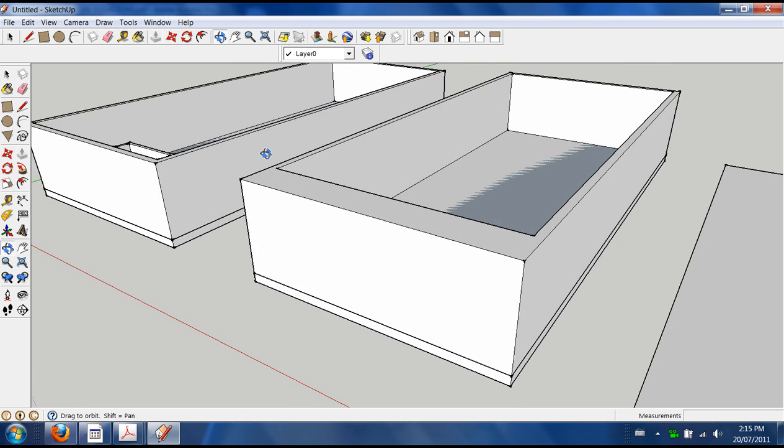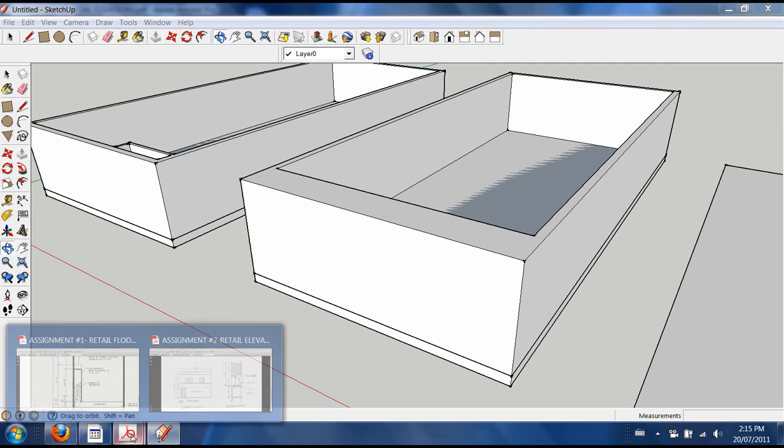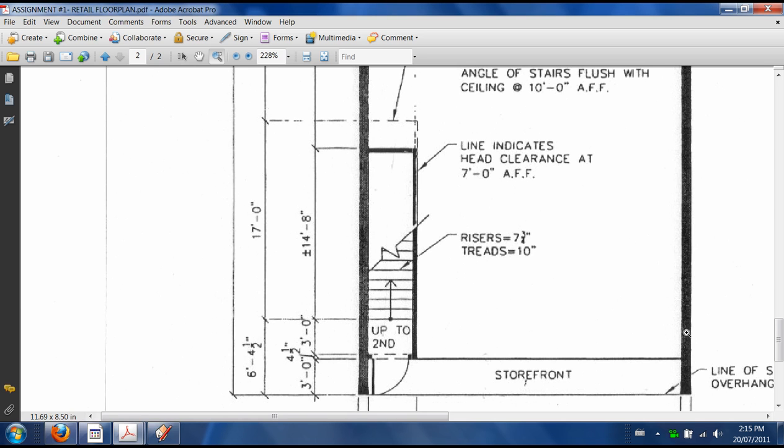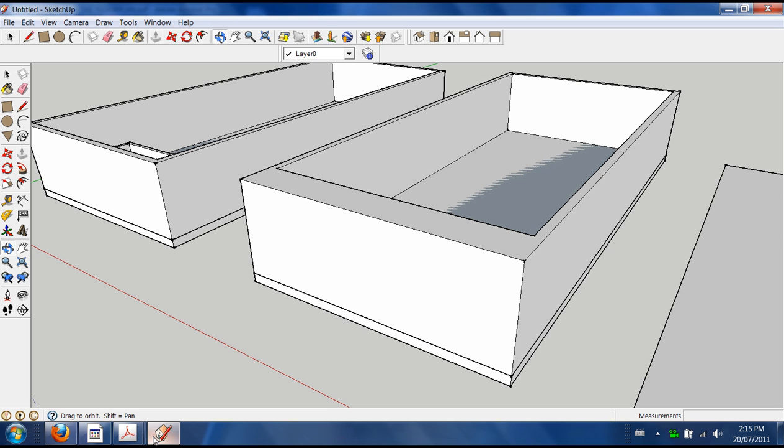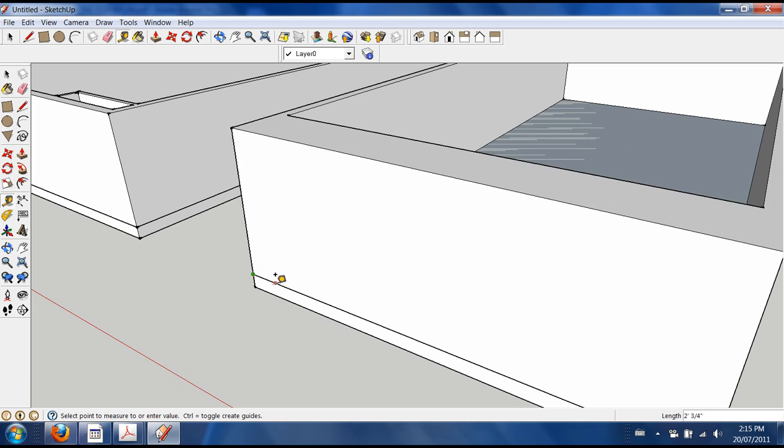And I want to draw a rectangle here that I'm going to be able to push back, because the two walls are still on the sides, as you can see in this drawing here. These two walls are still on the side, so I just want to push back this area here by 3 feet. So I'm going to use my tool. I'm going to click on here. Oh, not there. I want to make sure. I'll zoom in. I'll click on here, and I want to go across by 10 inches. That's the thickness of the wall.